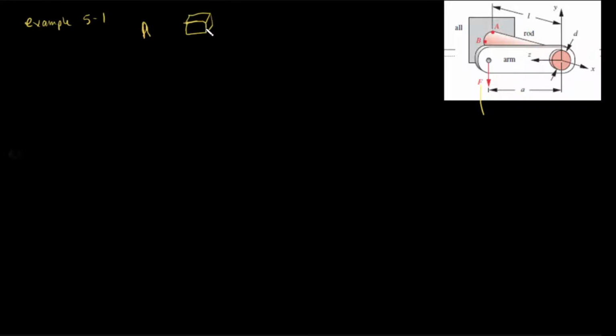On this stress element, we have this shear stress due to the torque. This is our tau xz, and it is equal to TR over J from our shear stress equation from applied torque. We also have a normal stress there, which we'll call sigma x, due to the bending stress at point A, and that is equal to our flexural formula, Mc over I. So we have this axial stress due to bending, and that shear stress due to the applied torque.